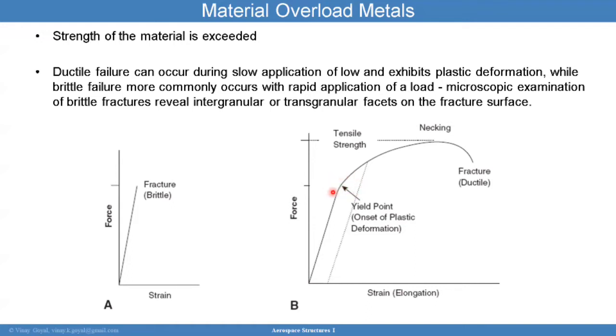And that's going to cause a significant amount of nonlinearity, which means that the more nonlinearity you have, the more ductile the response is, and the more strain energy under the curve, and the more advantages you have there for crashworthiness protection for an aircraft, for example. And so I want to point out that